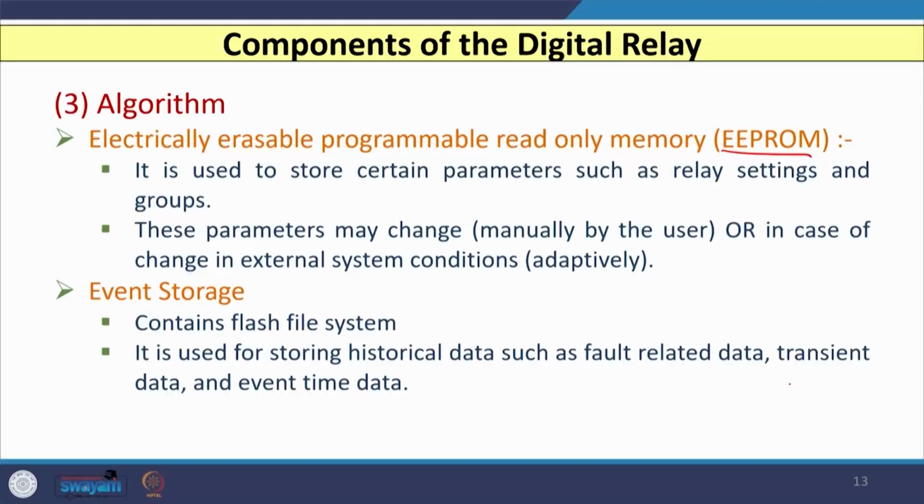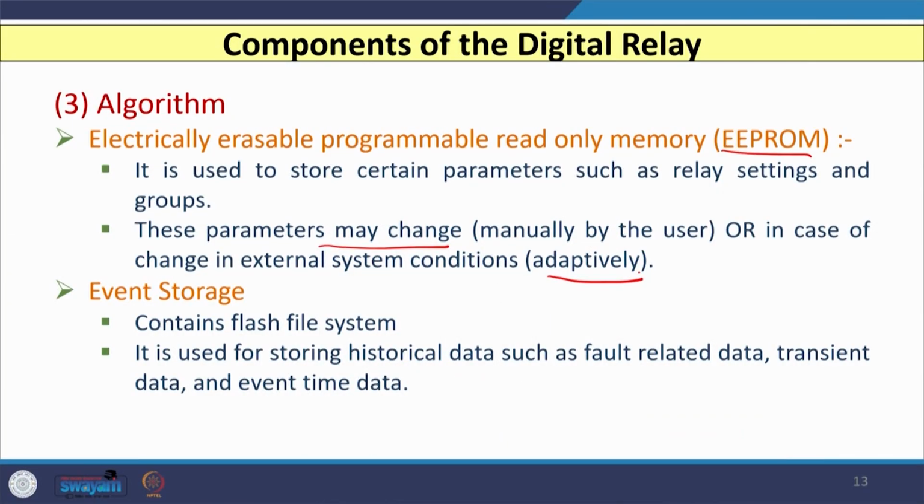Moreover, in EEPROM the parameters, that is relay settings, plug settings, time dial settings, can be changed manually by any person or engineer working in the utility. Let us say I want to change these parameters from x value to y value. So, that can be changed, or if any external system condition changes, then it can be changed adaptively also, this is also possible. Then we have the event storage block.